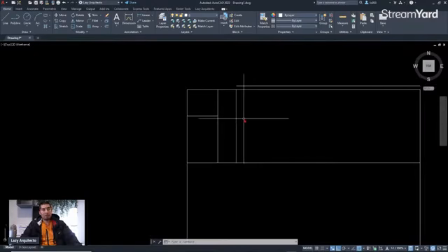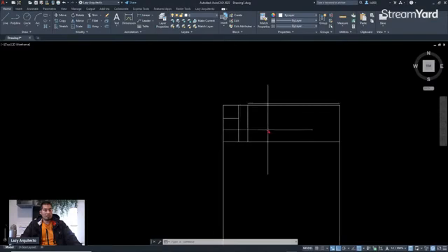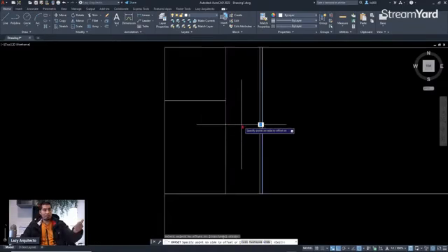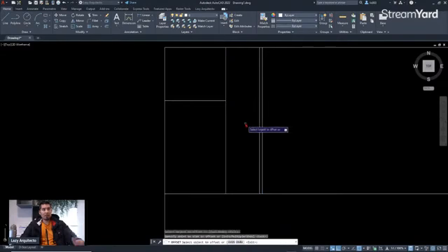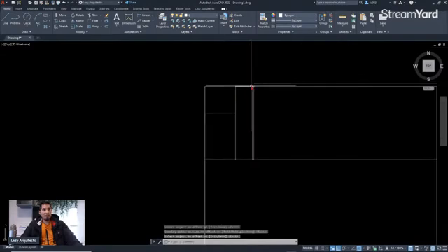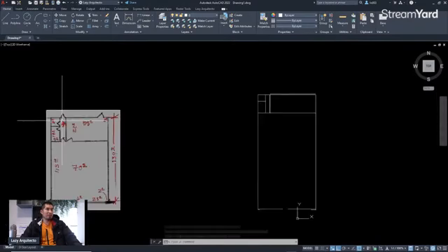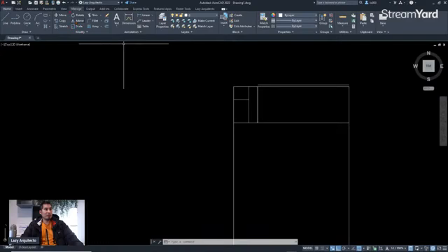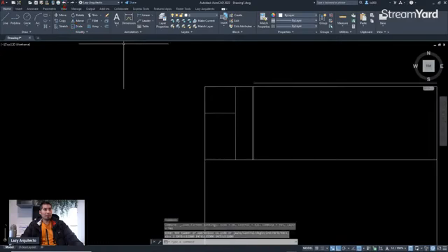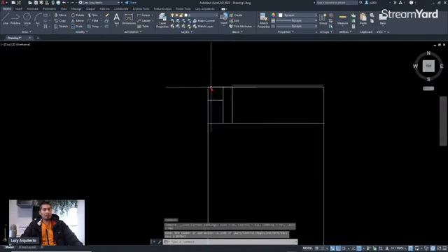So now if you offset this wall 5 inches, so let me do it, offset 5 inches. You offset it to the left, right? You're gonna lose 5 inches over here. So we don't want that because we have 5 feet 6 over here. So let me undo that, clicking this arrow over here.